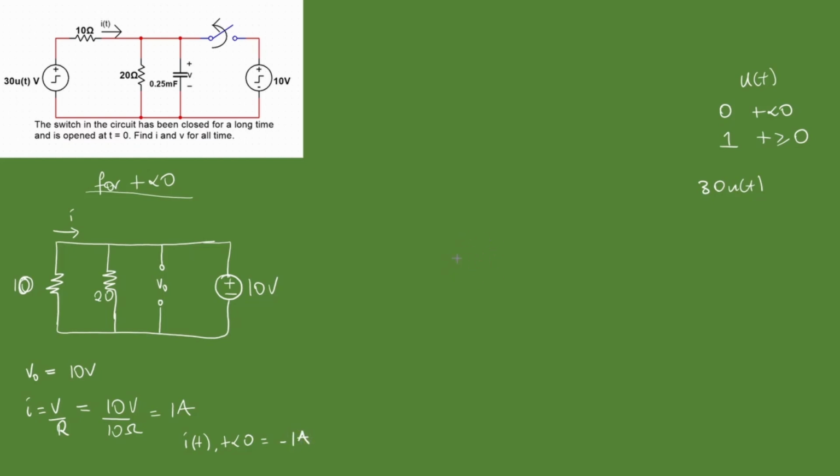You've got Ohm's law. Let's see what this was. Plus, negative. And you've got a resistor here. It's a very simple case. Let's call this 10 ohms. Let's call this 50 volts. Say we were asked to find, what is IA? Let's call this IA. What is IA? Ohm's law is very simple. I is V over R. So we're going to do 50 over 10, which is 5 amps. That's the current flowing this way.